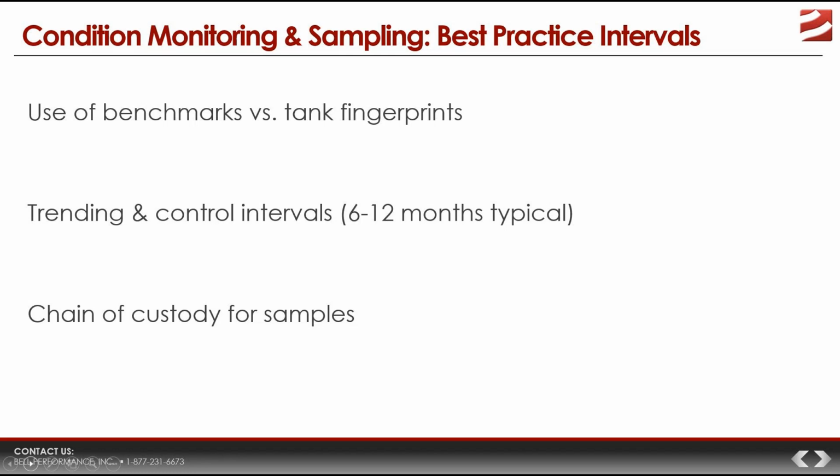In general, they tend to have a trend where they rise over time, but it's not completely linear. So, over time, you see your microbial levels rise steadily, and eventually you see the point in time at which they exceed the threshold for defining, hey, we've got a problem, we've got to do something about this. And that point in time is your control interval. It's basically how long it takes for microbes to rise to problematic levels in a given tank.